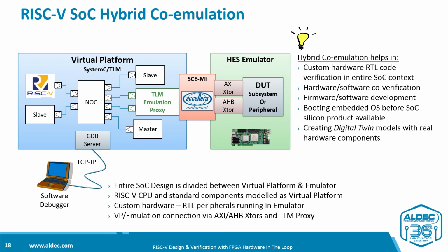In our example, the virtual platform contains a RISC-V CPU subsystem along with some standard components which are available as virtual models, and also interconnect. SystemC and TLM compliant simulators are typically used to model virtual platforms.